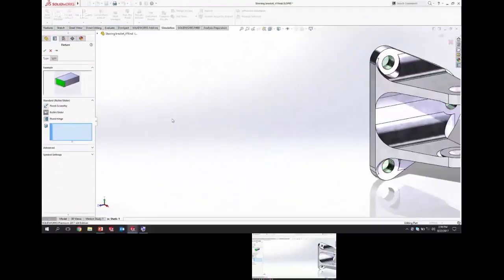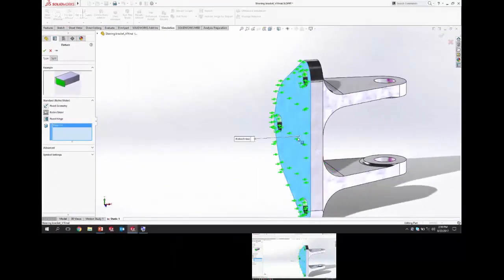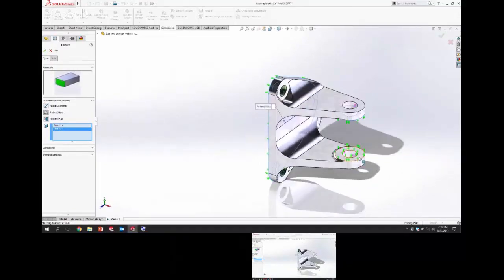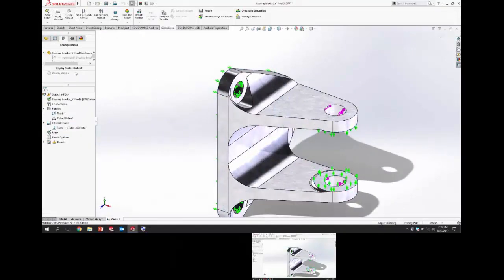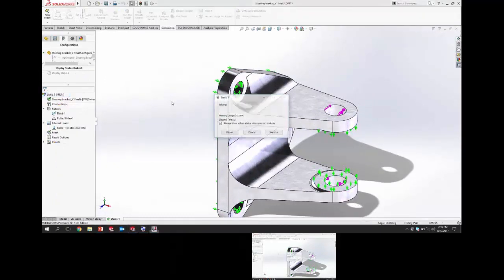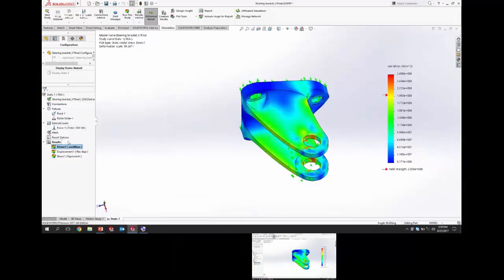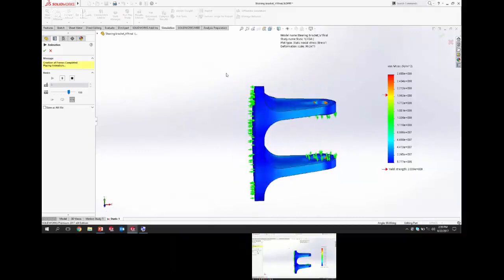So I'm just going to say, hey, that back face, I'm going to put a roller slider restraint there. And on these 2 flat faces there, little discs, those will now not be able to move out of plane. So what kind of results do I get? Now I get much more of the flex that I would expect without a lot of that additional distortion.